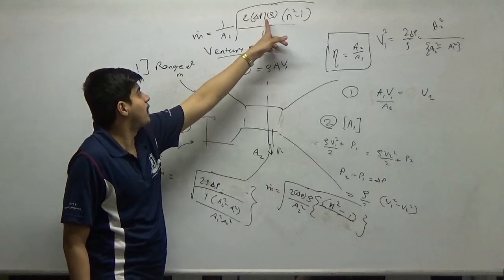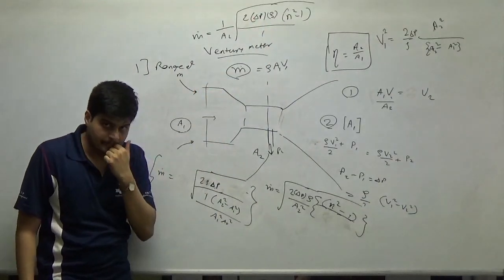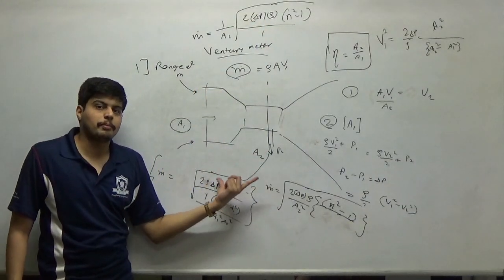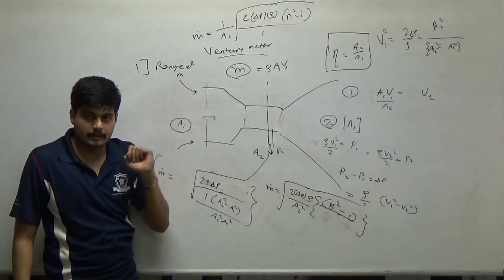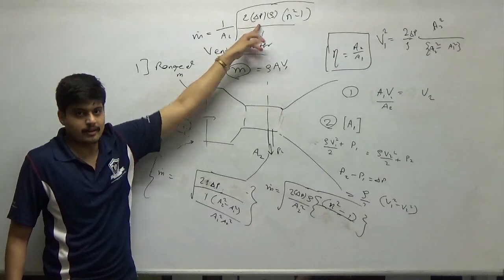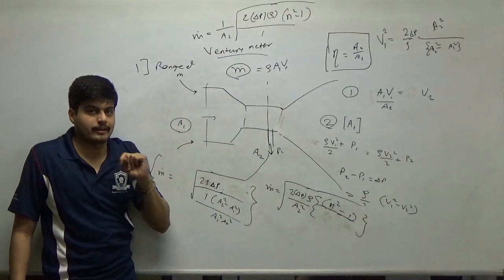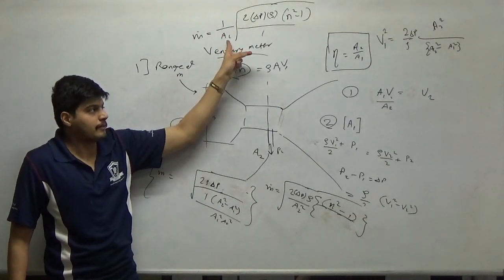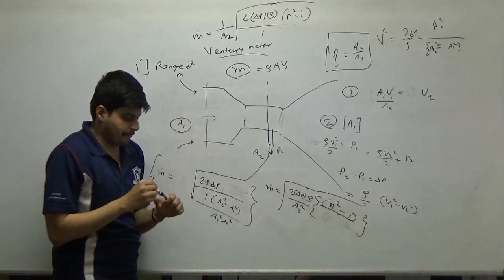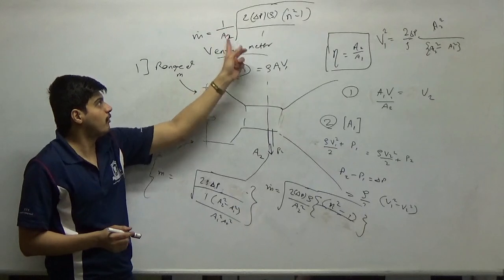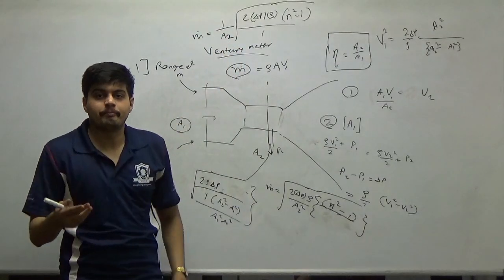Second experimentation part is the delta P tapping. More the sensitive your pressure differential reading is, better the mass flow readings that you get. If your delta P has an error, m dot also has a proportional error. Third is A2, right? As you make A2 smaller, the error in 1 upon A2 keeps going up.